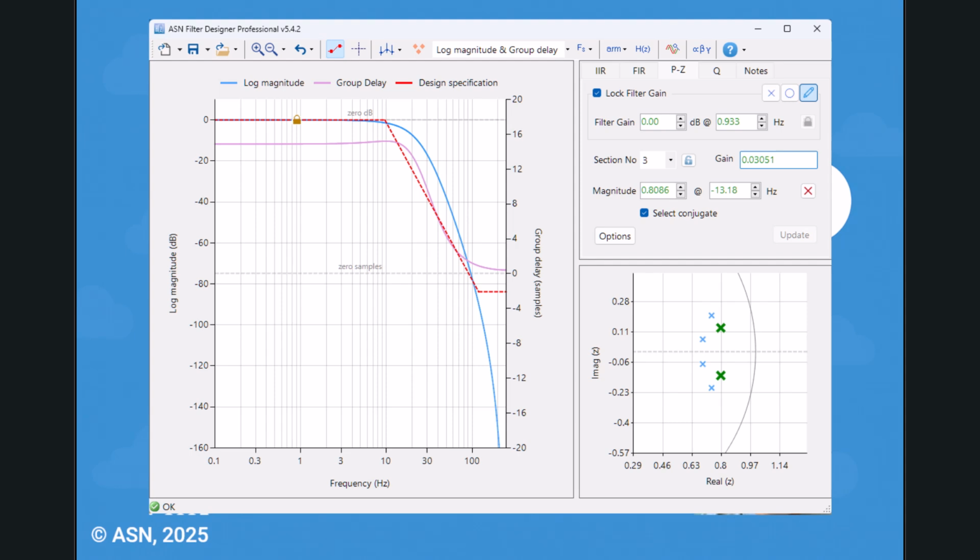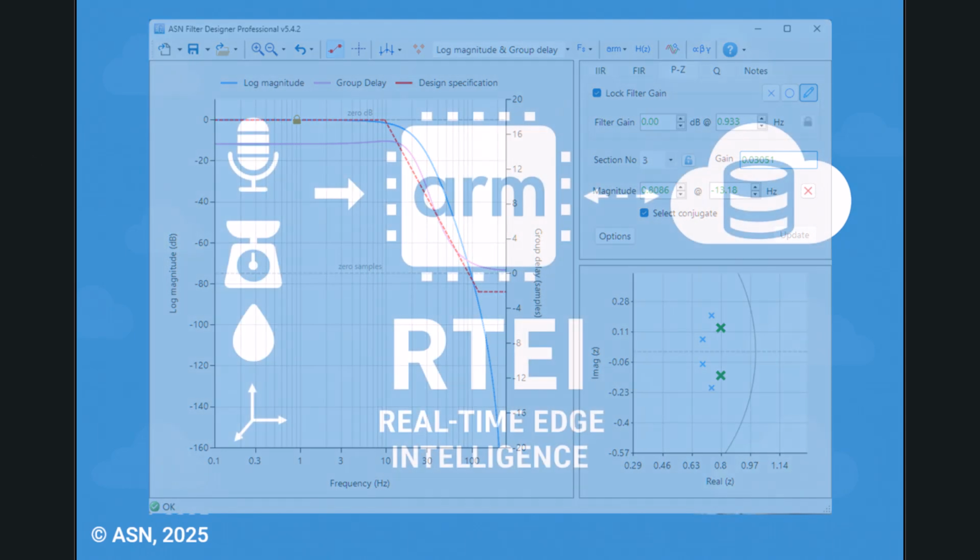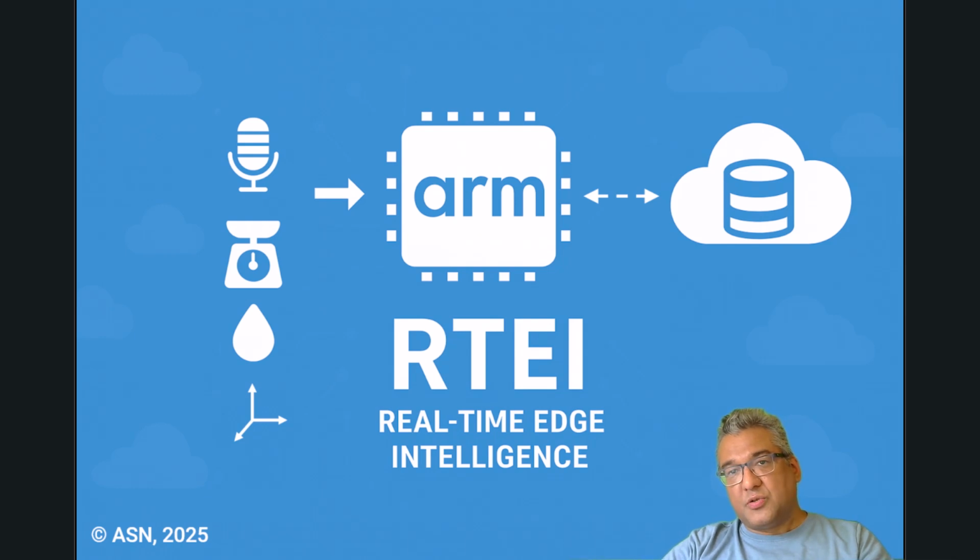Although this adjustment does alter the magnitude response slightly, it improves the passband phase response, which in turn flattens the group delay, making the phase almost linear without the need of adding an all-pass equalization filter cascade. This not only reduces the ringing in the step response, but also helps maintain the harmonic relationships in the passband, which is why the waveform shape is much better preserved. And more importantly, we still maintain sharp stopband attenuation, ensuring that this is still a decent low-pass filter.